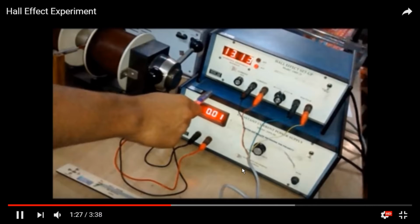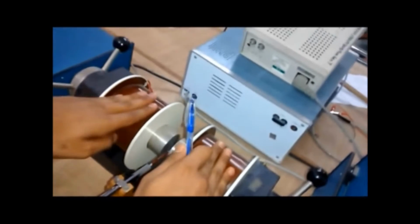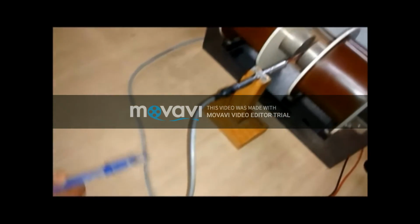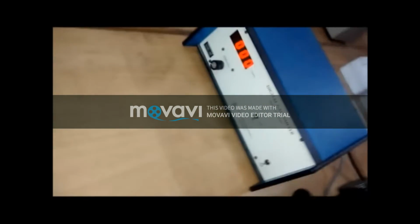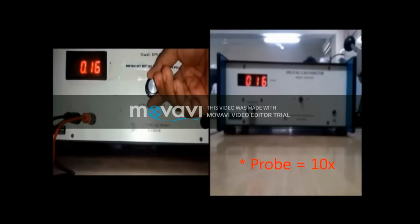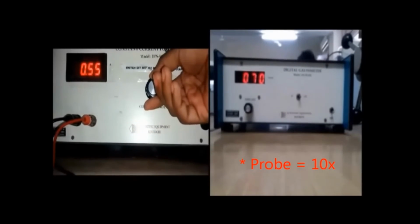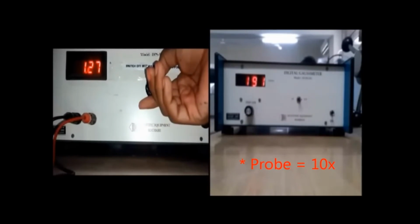Current is applied from the constant current source, from where it flows through the wire to the pair of electromagnets. A magnetic field is maintained between them. This sensor measures the magnetic field and is connected to the Gauss meter, where the magnetic field is displayed. Vary the current in the constant current generator such that the magnetic field between the poles of the electromagnet becomes 2000 Gauss.